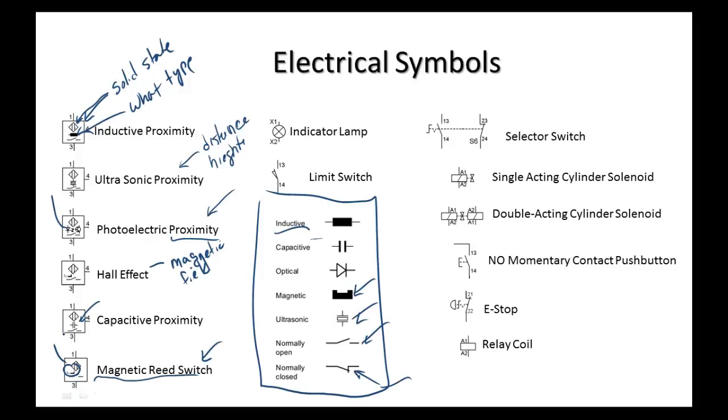That could be a reed switch, and what they're probably doing is the PLC knows the size of the magnet. When the thing moves by there, it's going to open and close. And probably in their PLC they've got a timer circuit, and they say, okay, if it lasted 3 seconds, you had to be moving by this fast. I imagine it's nothing but a reed or a Hall effect.